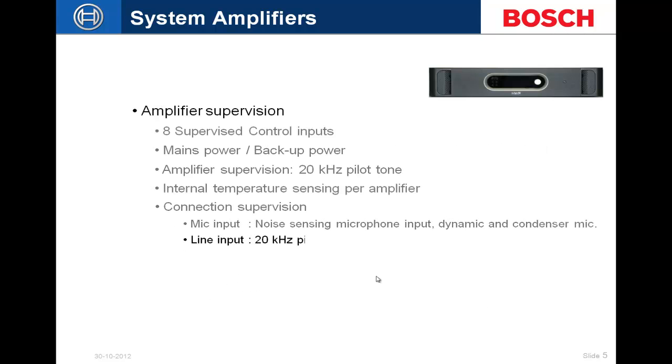Built-in amplifier supervision for mains and backup power. The amplifier supervision for 20 kilohertz pilot tone you can enable or disable within the outputs. Internal temperature supervision and connection supervision for any AVC microphone that I put in. Also a line input pilot tone detection as well.